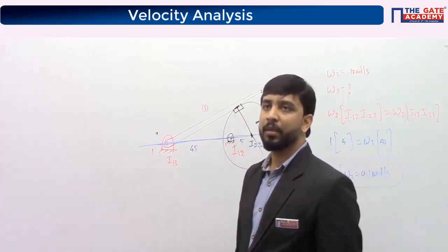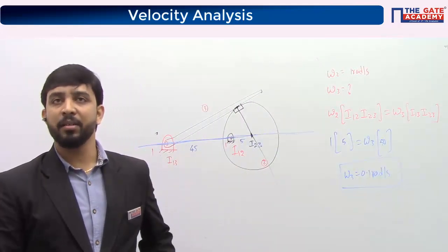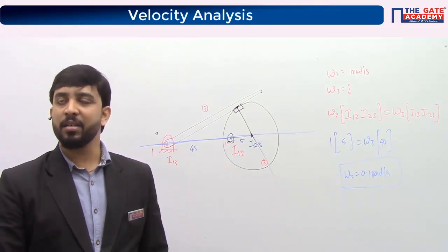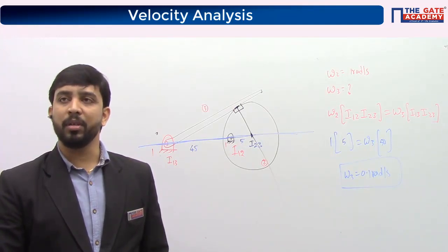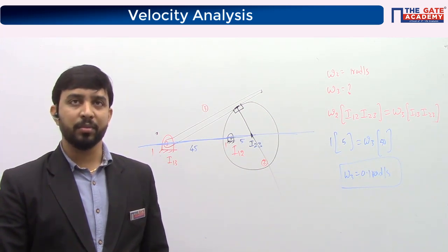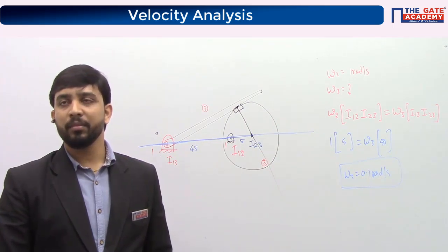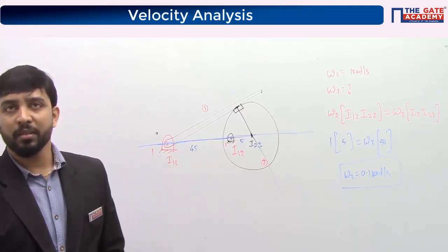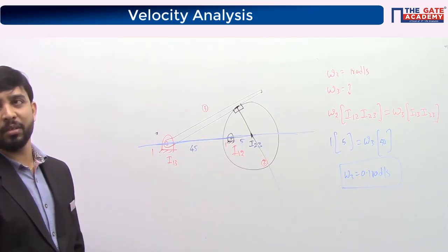the common normal, okay? So the polygon trick is not required here. Here only 3 I centers are there, right? If you have more, say 6 I centers, then it's difficult to locate, and there we go for the polygon trick, if the number of unknown I centers is more. If there are only 3 I centers, you draw a triangle and all 3 lines are connected, so the polygon trick doesn't work here.